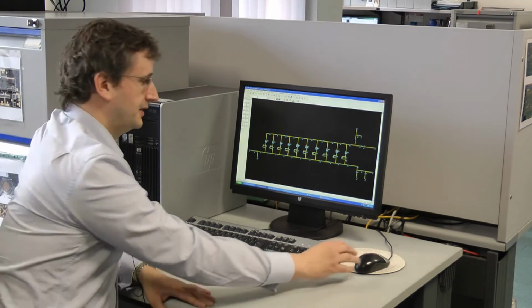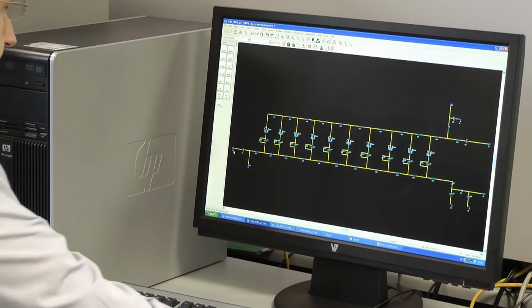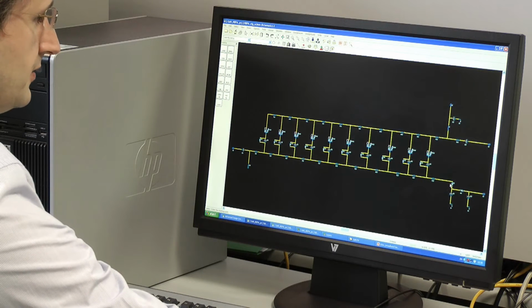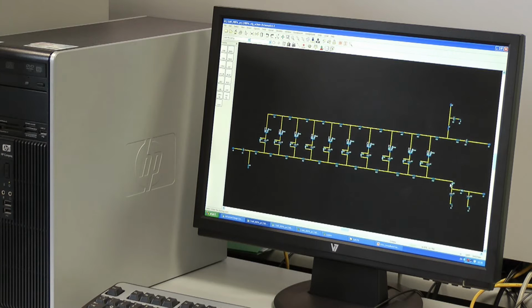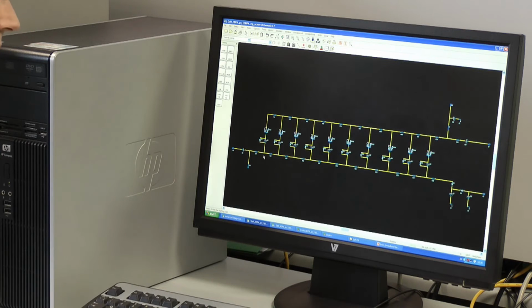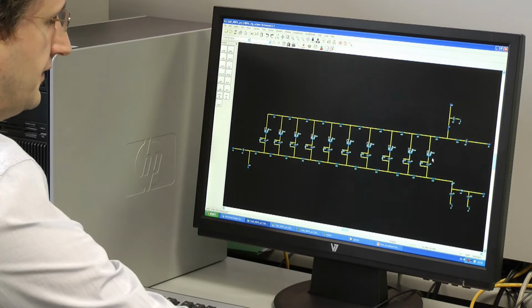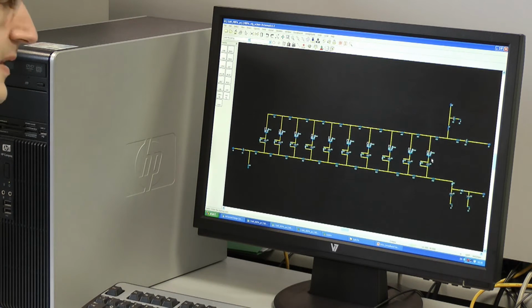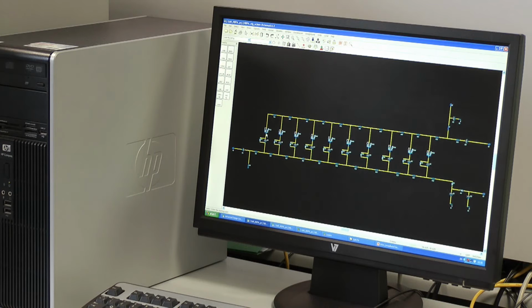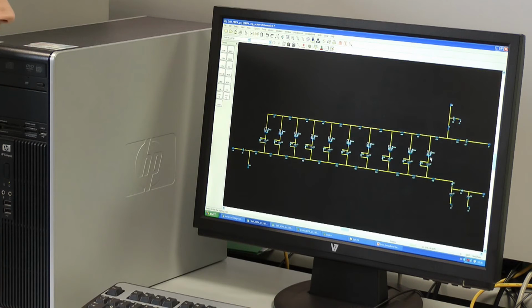In a distributed amplifier, as we apply the input signal here, it propagates along the gate line toward the termination resistor. And as it does so, it gets progressively attenuated. This means that the device nearest the input is driven harder than the device near the output. So, under large signal conditions, this device near the input will compress sooner than the other devices.